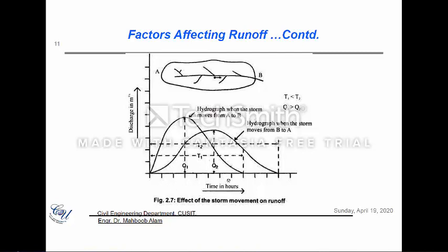So this period is then quite longer. You can also see that time 1 is less than time 2, and also the peak is shorter, because you see this precipitation which is occurring here, it is getting out of that catchment very quickly, so it is not contributing to that precipitation which would be coming after some time from the further areas.